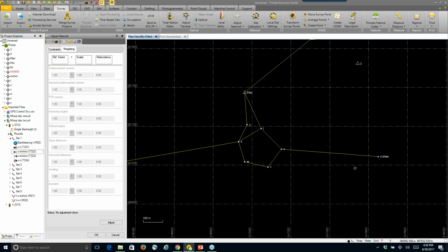If you have RTK data, it's going to use a weighting scheme. When you collect RTK to use in the network adjustment, you save the QC1 and the QC2 report, and it's going to use that information to weigh how it's going to be adjusted. And that single observation is what's going to be used for the position. Unlike here, where we have this observation between U and T, but we also have other ways to compute these 2 points. So when you do a least square adjustment with side shots, it will adjust the optical side shot points, but only with respect to how the setup and the backsight were adjusted. Hope that answers the question.